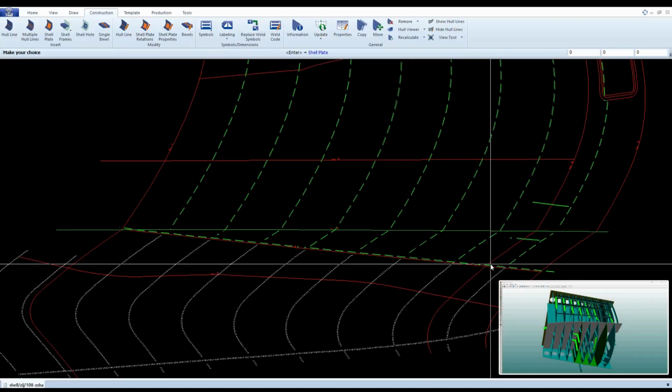The development done in the year 2016 for the new shell plate implementation totally changed the shell plate definitions and the unfolding method. This new method will not give the same results as the previous system. In the previous system, shell plates were generated based on the calculation lines, which were part of the input. In the new system, the keyword in the process of shell plate creation is simplicity. It is exactly as for regular plates by choosing the borders of the desired shell plate.